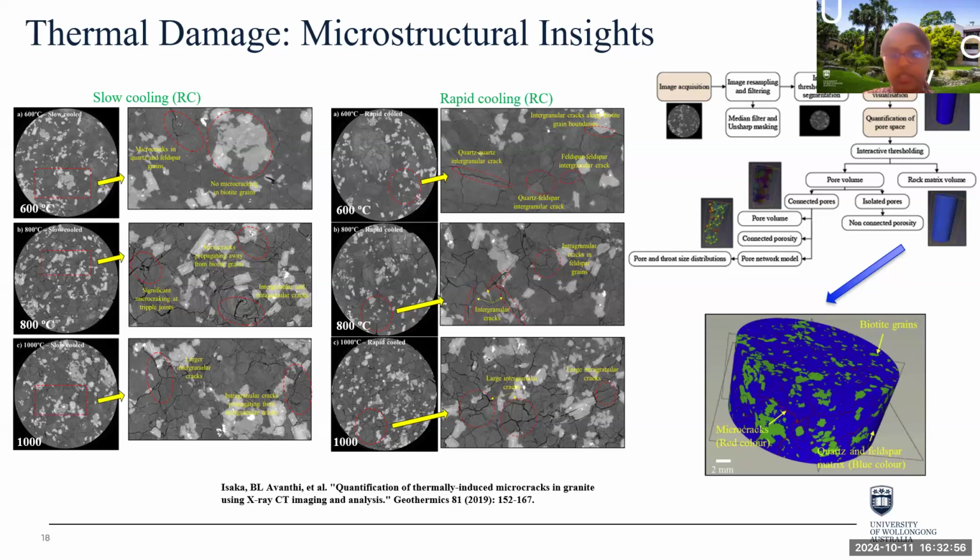We identified minerals and cracks by examining contrast and brightness in the micro-CT images, where density affected intensity values. Then a multi-thresholding segmentation technique was used to separate individual minerals and pores, providing a detailed view of the rock microstructure. I will talk about the steps of constructing the 3D structure employing 2D images and pore network modeling in the coming slides.